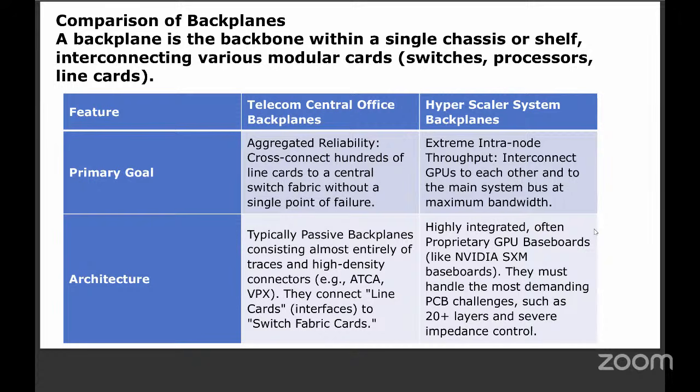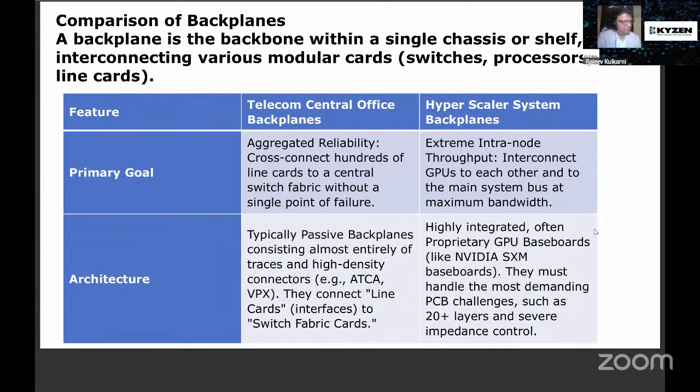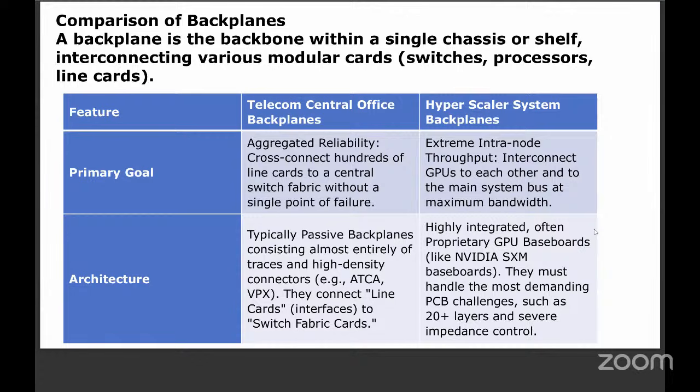They must handle the most demanding PCB challenges such as 20 plus layers. This is my field. 20 layers plus. Today 20 layers is like what a 6 layer was 20 years back. When multilayer went from 4 to 6 layers, it revolutionized. But now we have to use 20 layers here, and very tight impedance control.